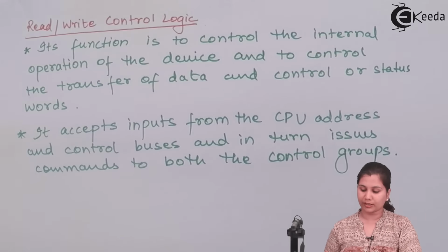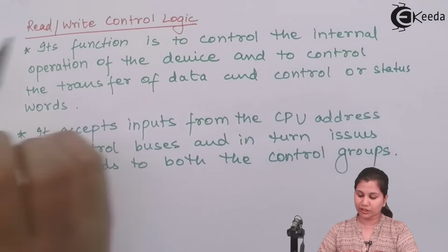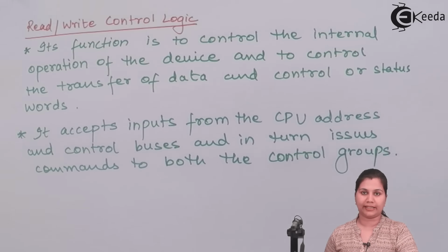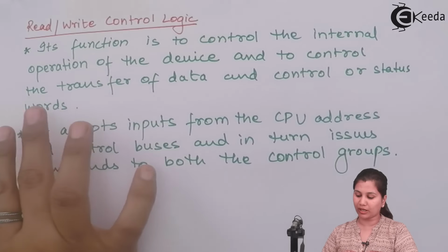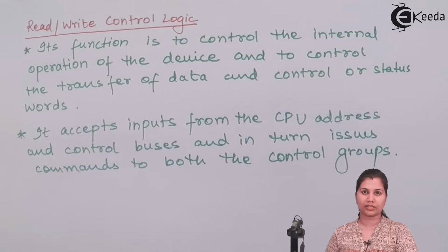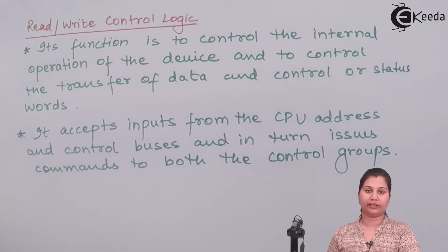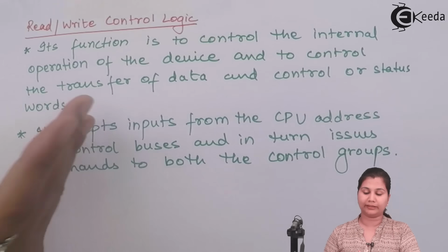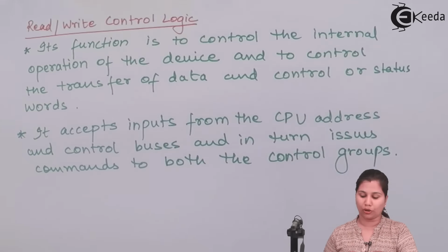It controls the internal operation of the device, that is the 8255, and controls the transfer of data and control or status word. So whatever data is read from the ports or written into the ports and the control register, all that information is controlled by the read and write control logic.